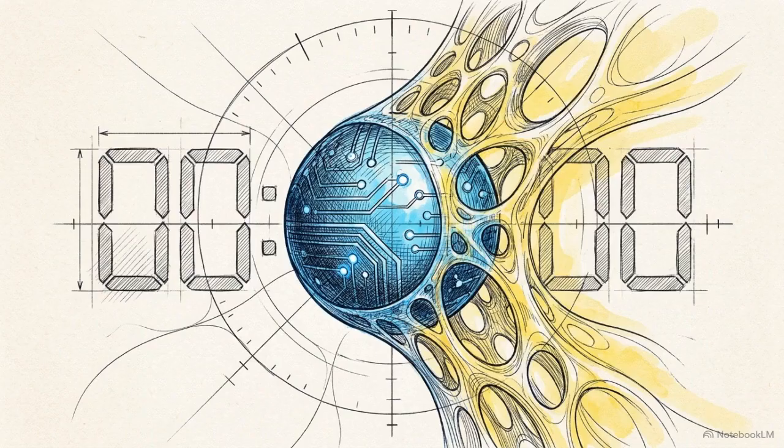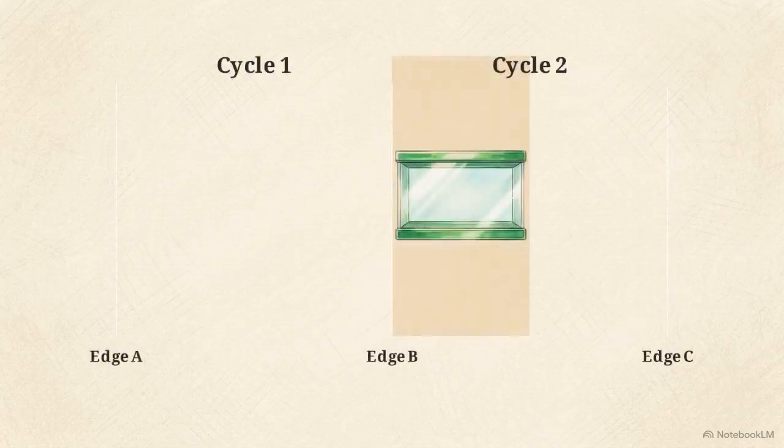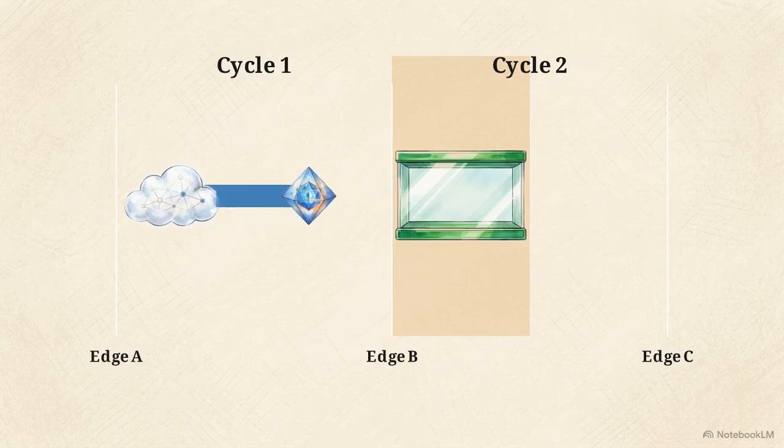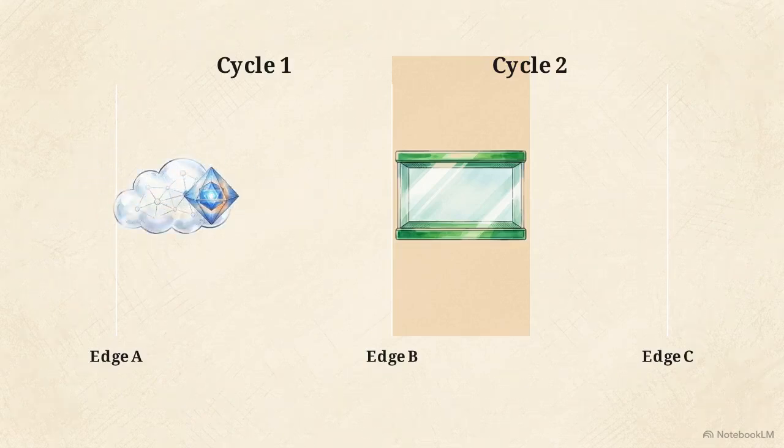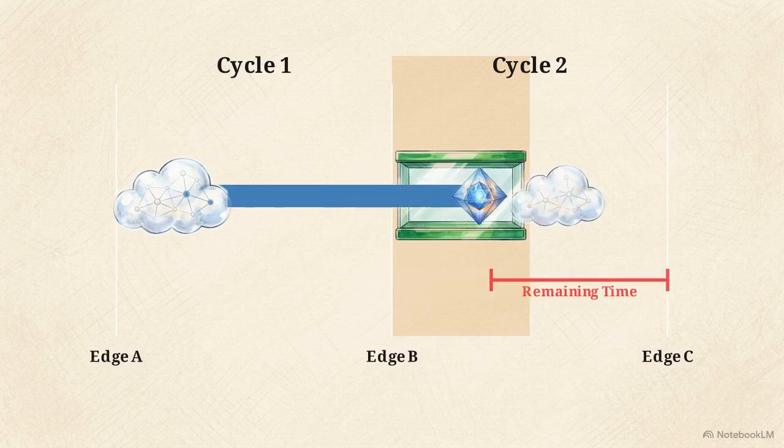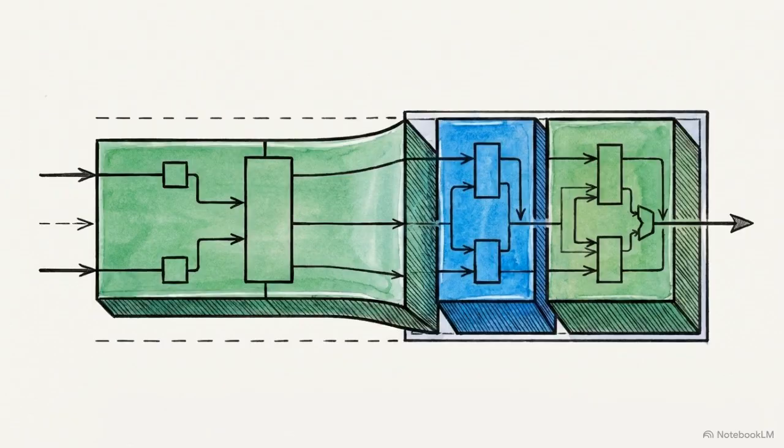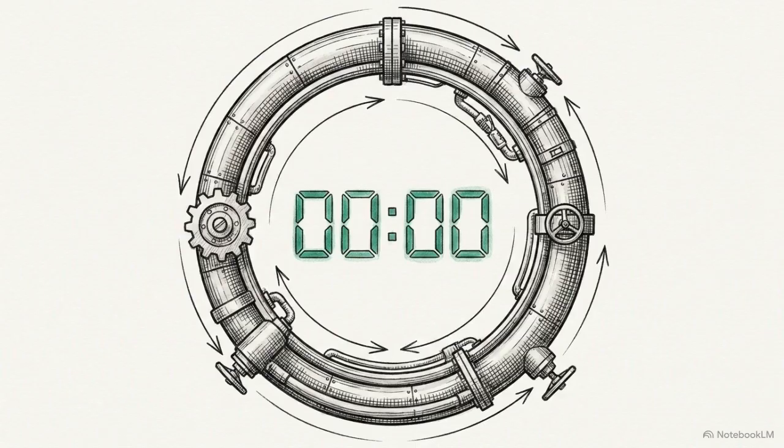Because a pure latch relies on a wide, transparent window rather than a hard edge, an unusually slow logic path isn't forced to halt exactly when the clock ticks. The slow calculation is allowed to bleed over the half-cycle boundary. It physically borrows time, continuing its computation while the receiving latch is transparent, eating into the time allotted for the next stage. There is one strict mathematical caveat to this flexibility. While individual loops can trade internal timing deficits back and forth, the entire pipeline sequence must still resolve and balance out within one overall clock cycle.